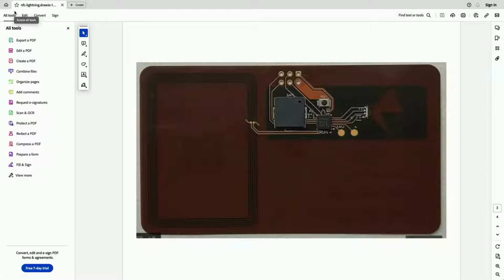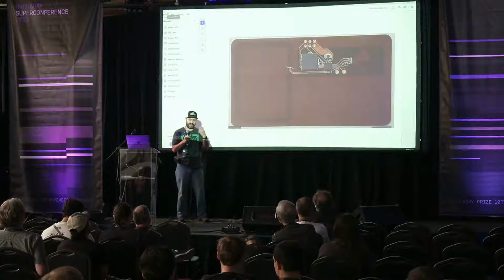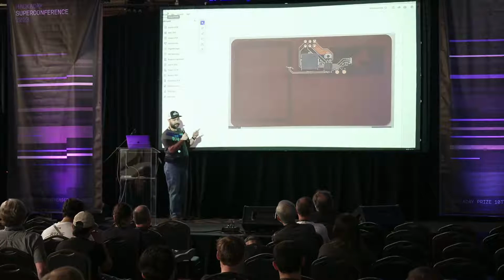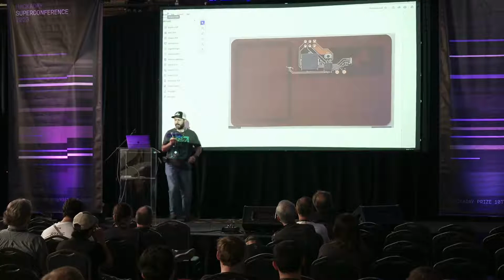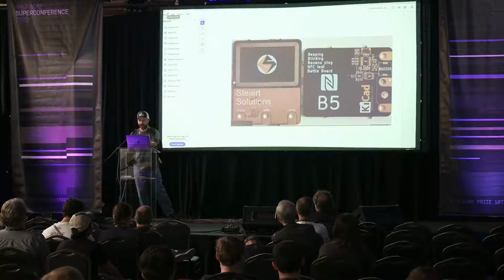So that is the circuit, and if I go to the next one, this is the Flex iteration, and the circuit on back is really simple. NXP makes an NFC microcontroller that has a tag built into it, so it's one chip, and then I was able to program the micro to do the beeping, and there is an LED here, but one of the things I learned about this micro is that internally it regulates the NFC voltage down to 1.8 volts, so that was only enough to light the red LED, so this one can only be red even though there's an RGB LED on that.